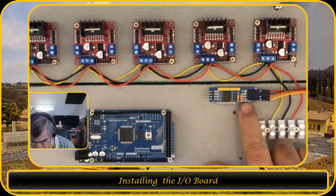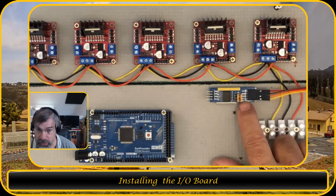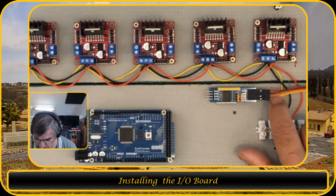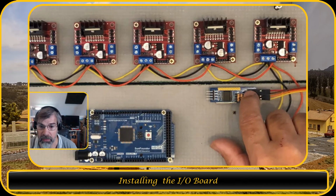And that is the connection for the I2C bus. That's the clock, that is yellow. The SDA, that's the data, is orange. Then we have the ground. And then we have VCC, which is 5V.